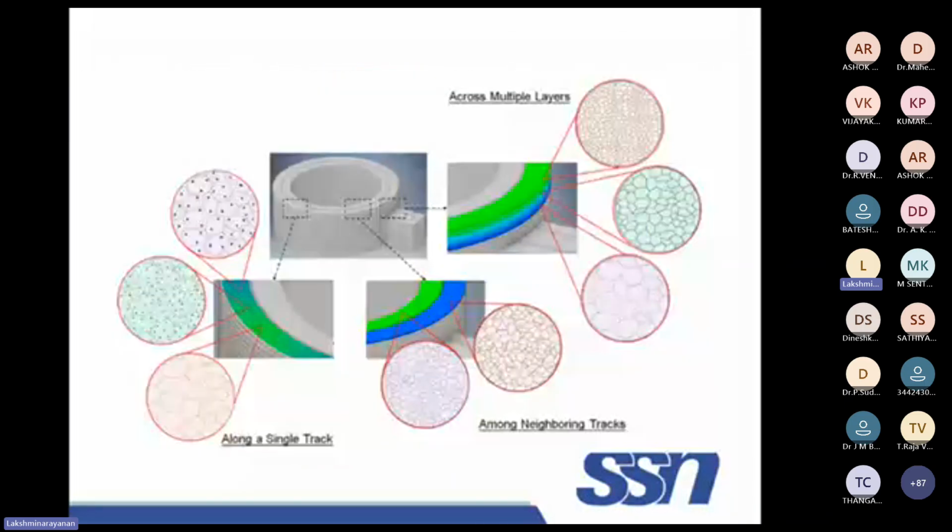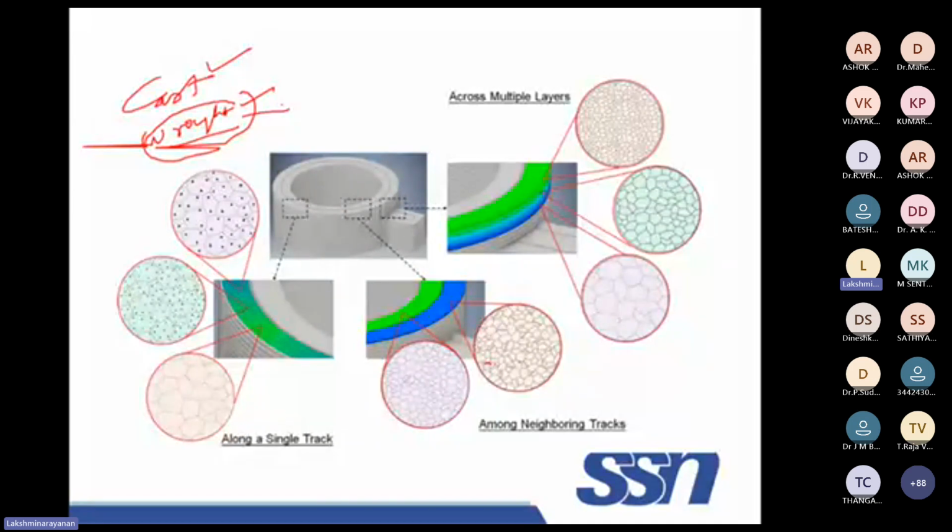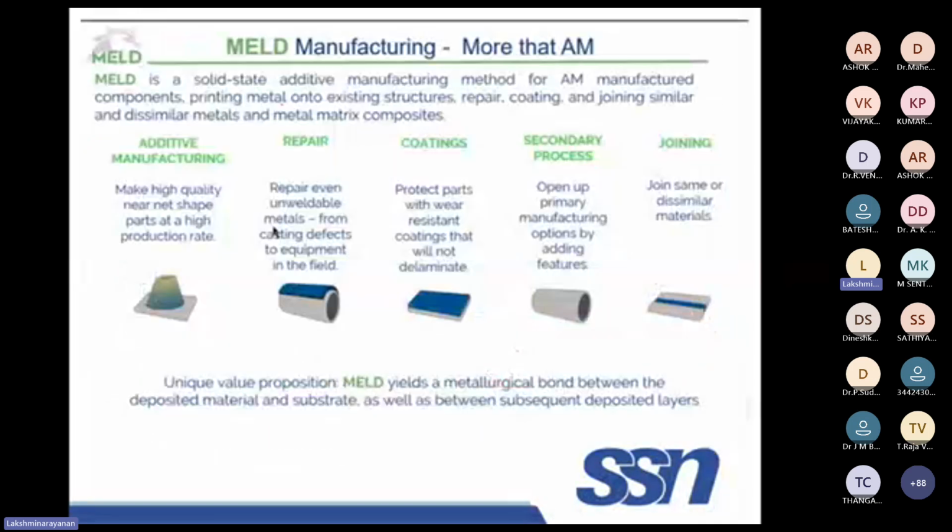It is even like a wrought structure. Basically, microstructure. If you see cast structure, wrought means secondary process. That means deformed. Cast means just melt and solidify. Always use wrought for better properties. So that is why these are some of the cylinders.